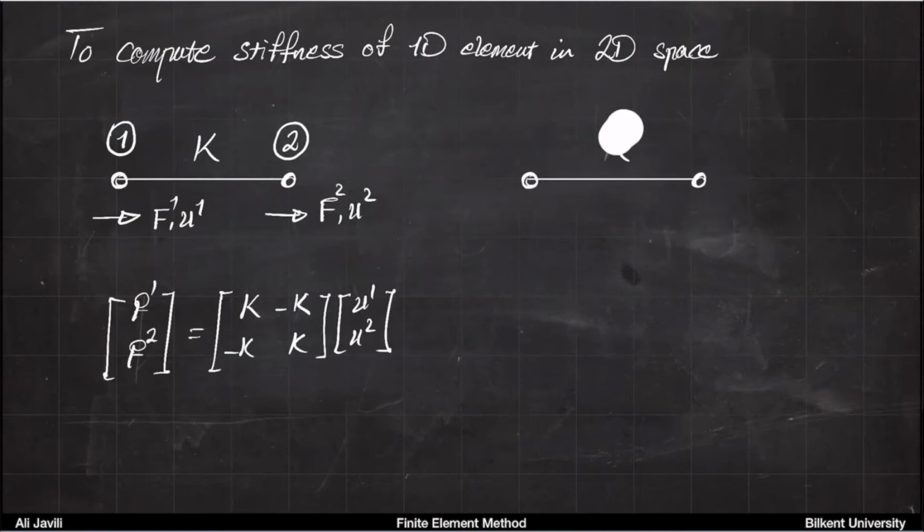And now I will just turn it a little. So it's the same thing. I'm just turning it. This is the problem now. And you can imagine as soon as you turn it, the element stiffness itself, let's say it's a spring, is the same thing. It's the same element. It's just still K. But if you think of this as node 1 maybe, and this is node 2 now.